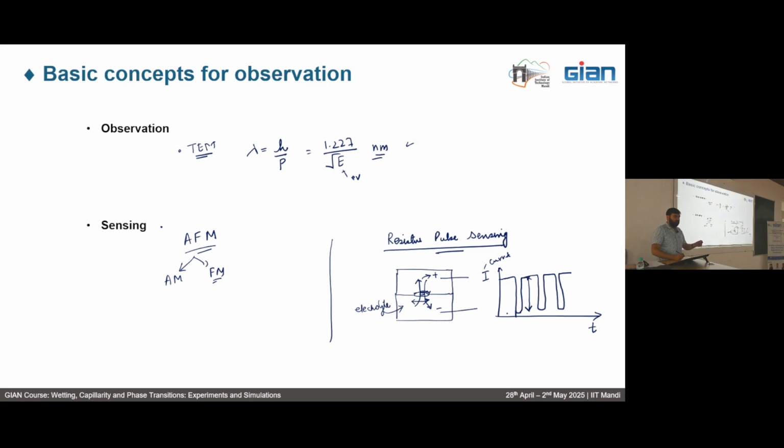If we have a small nanobubble that doesn't cover the whole nanopore, or if we have a bubble just above or below this nanopore, even in that case we can say that the channel is not 100% blocked. It means that the dip in this current signal is not as large as when all of the channel is blocked. So these are certain basic concepts for observation of nanobubbles.